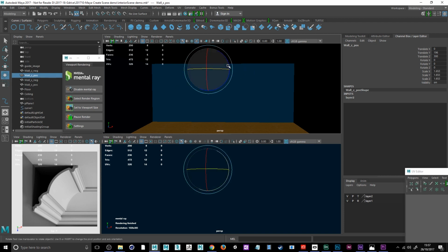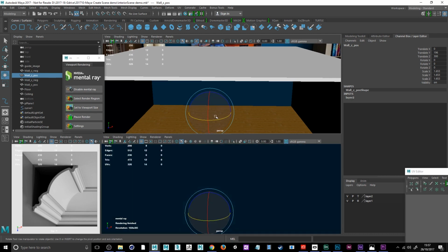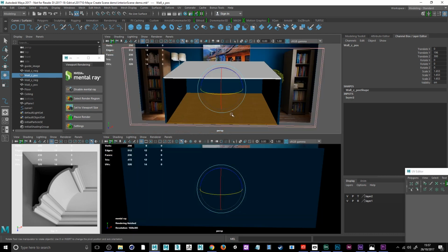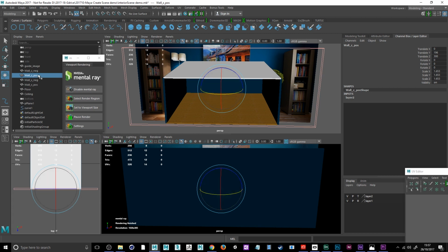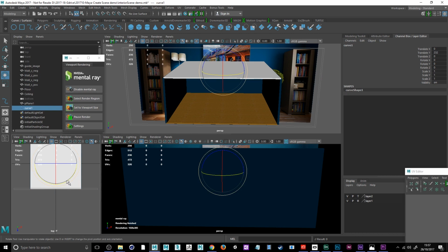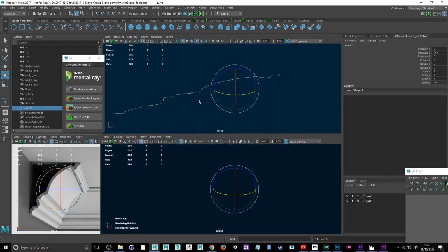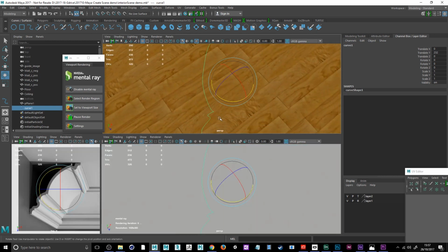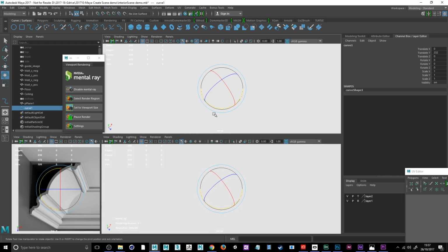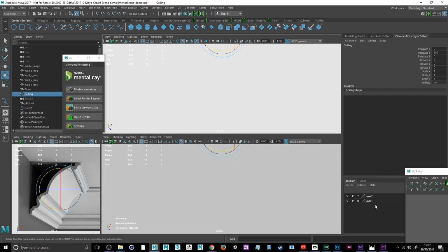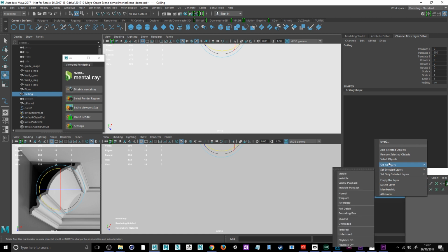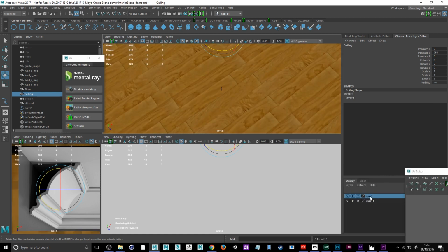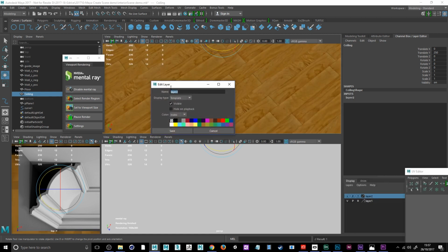Now this will need to rotate because it was a flat piece that I worked on. I have just zoomed in on it. Zoom in on it here as well. That's the wall I want the curve. So I'll press Shift and F, and it should come up in each of the windows. So the ceiling's actually there as well. So I'm going to add ceiling to this layer. Double click it, and I'm just going to call that hidden.